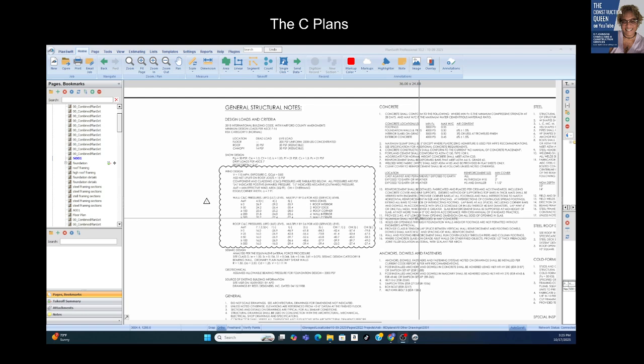Okay, and so the dead loads are basically just dead weight, right? Permanent weight. Okay, and that consists of the roof framing, the walls, the concrete slab, everything within the building is part of the dead load. Okay, the live load, that's temporary or movable stuff like people and equipment and snow and furniture.